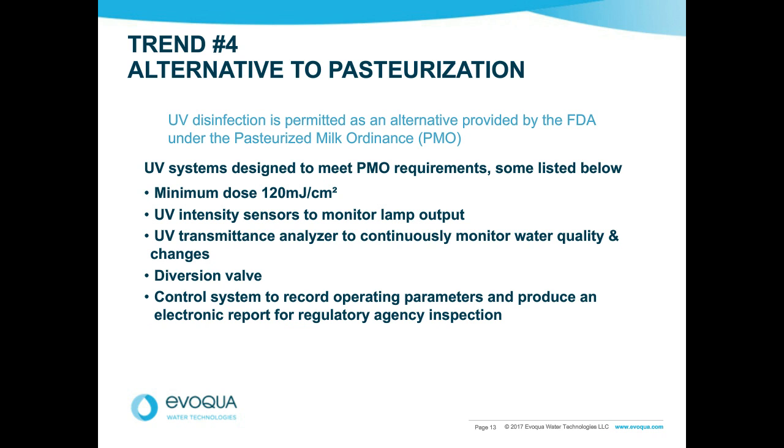If the system fails, it must fail safe. So there needs to be actuation of valves to dump the water. We cannot send improperly treated water forward. That's very important.